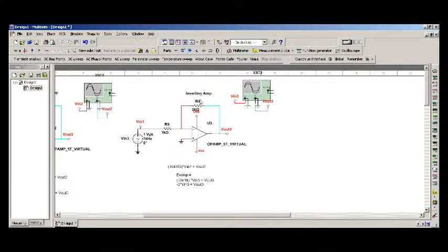And then last here, for our inverting amp, we have R4 equal to 2K and R3 equal to 1K. Well, negative R4 divided by R3 times Vn equals V out. So if we have 2K for our R4 over our R3, which is 1K, 2K over 1K is 2.